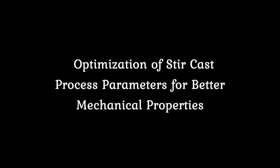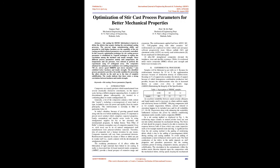Optimization of stir-cast process parameters for better mechanical properties. Abstract: Stir casting for HMMC fabrication is known to defeat the defects that are acquired during conventional casting processes. The near-net shape manufacturing ability and potential to yield higher hardness are capabilities of stir casting, provided technical parameters are accurately controlled. In this research, an optimization technique for stir casting process parameters is established by the Taguchi technique to explore the correlation between hardness and tensile strength.